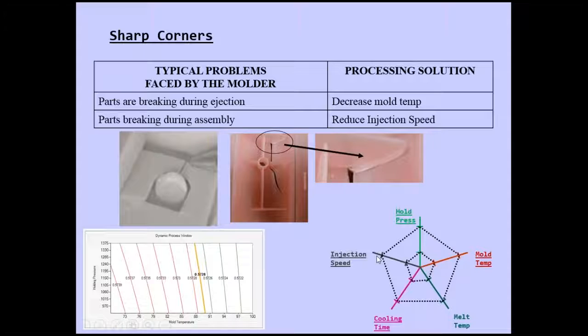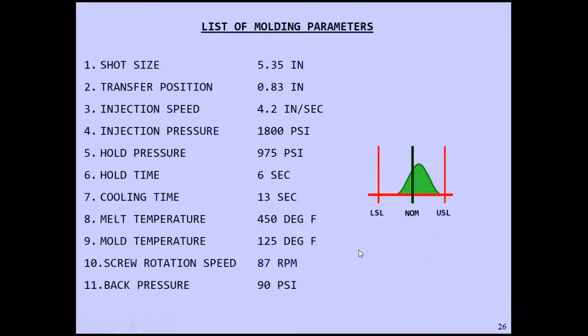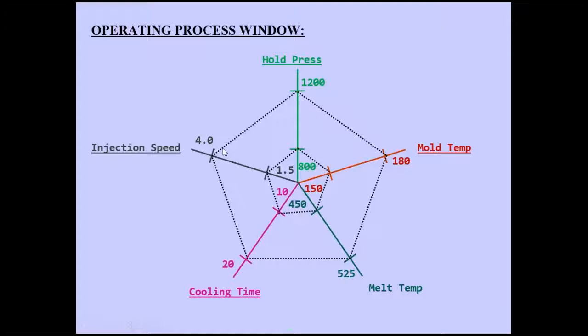But as soon as he reduces the injection speed, what happens? It goes into this area. It basically goes out of spec, right? If I go back to this thing here, he goes out of spec. He goes in this area and says, man, now I can't make good parts. Or he changes the holding pressure, which is the worst thing to do, right? He changed the holding pressure because, I'm packing it out so much, let me pack it less.